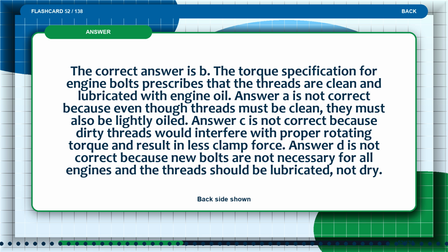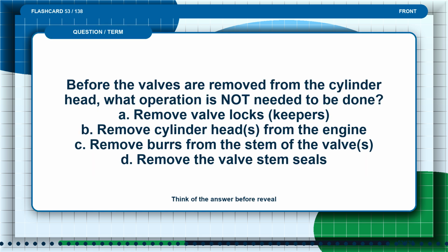Flashcard 53. Before the valves are removed from the cylinder head, what operation is not needed to be done? A. Remove valve locks (keepers). B. Remove cylinder head(s) from the engine. C. Remove burrs from the stem of the valve(s). D. Remove the valve stem seals. Pause and think of the answer before the reveal.